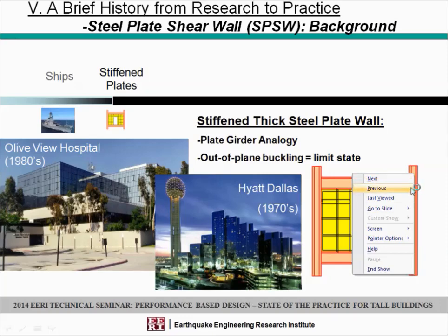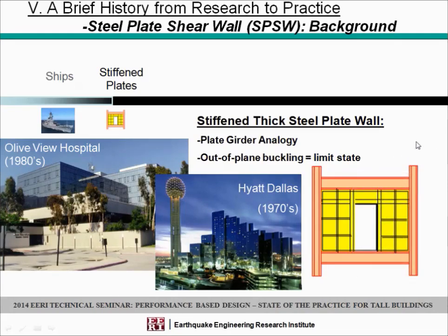So we resorted to a steel plate system in partition walls between guest rooms, and being lighter and not concrete, it was much easier to do the transfer. So we transferred the steel plate with open brace frames below grade. But that was the old approach, sorry guys, of what's called the stiff, thick steel plate approach.